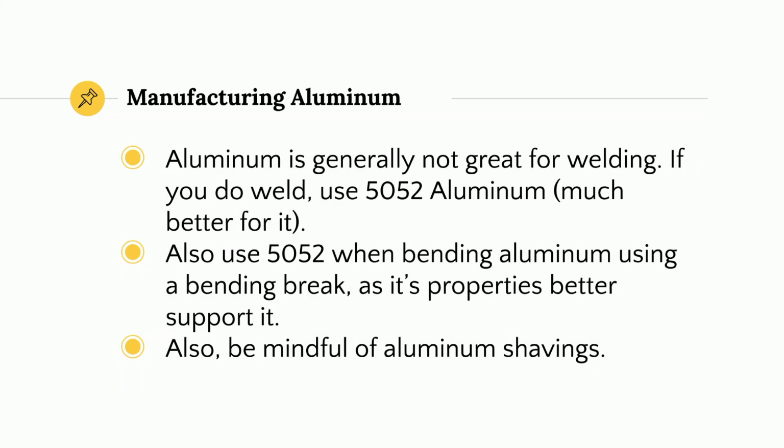Also, when you're manufacturing, be mindful of aluminum shavings. We'll go over this later, but it's important to not breathe them in, and to use gloves when handling parts with shavings all over, because they will cut you. Just be careful of them.